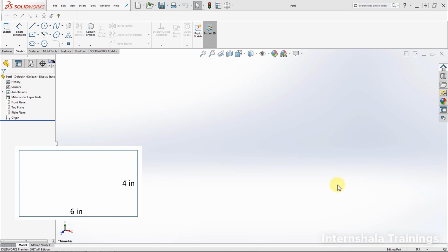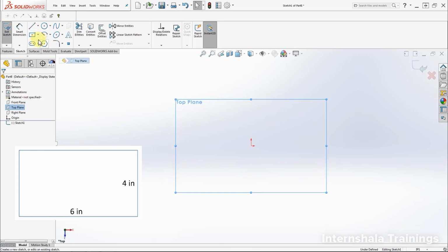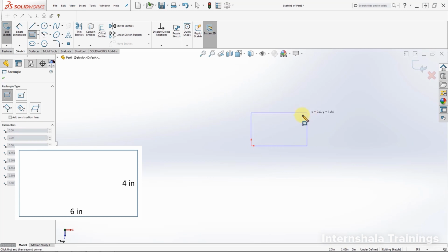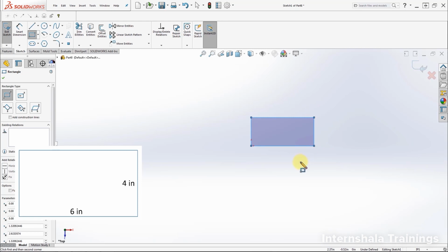We look at the bottom and see that the document is already set to inches, and so we will just leave it like that. We have already covered how to sketch a rectangle, so let's go ahead and do that real quick. Select a plane, go to sketch mode, click on rectangle, and draw a rectangle. For now, do not concern yourself too much with how big the rectangle is, because that's what we're doing in this lecture. Now let's go ahead and start dimensioning this rectangle.